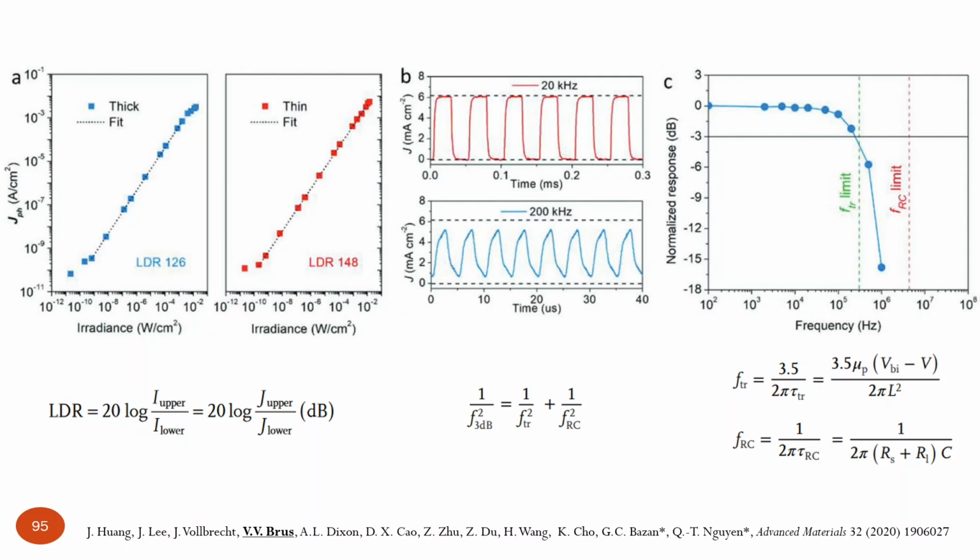It is important, since we use photodiodes for calibrating, for measuring light intensities, we want to have linearity of its light intensity dependence in as wide an intensity range as possible, not spectral but intensity range. And you may notice that in photo cameras you also have this parameter, linear dynamic range. It actually tells you how realistically it can show you an image where you have regions with very dark and very bright areas. So you don't go to saturation in bright areas and still see something in dark areas. So you have this gradient with details which you can still distinguish in bright and dark areas.